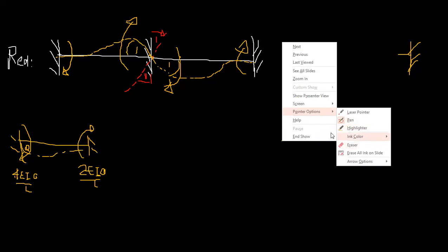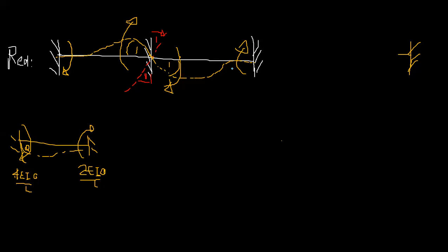And we can work out the directions as well. The easiest way is to consider what this beam is trying to do. This beam is trying to push this position in this way, so it needs to keep it back, and the reaction should be in this direction. Compared to this location, it tries to bend this beam in this way, so the reaction should be in this way to keep it in position. Compared to this location, this tries to move the beam in this way, so this end will have a reaction like this. So these are going to be 6EI.